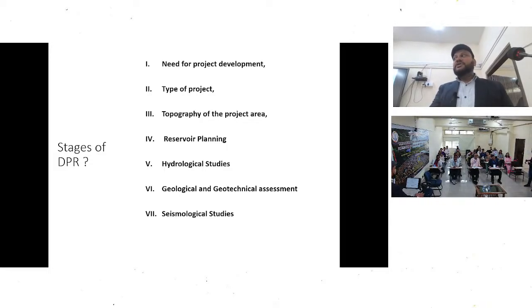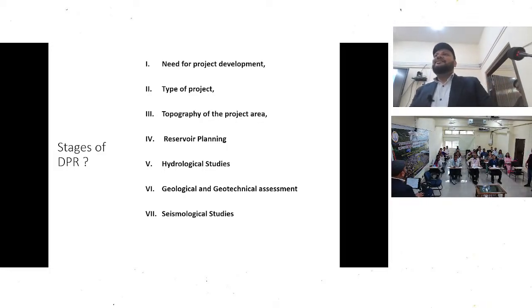The topography of the project area: if we want to construct a dam in, suppose, a plain area, Majuli or some Guwahati, then what will happen? The reservoir will inundate whole Guwahati, the whole area. So it is not feasible. And we have to plan reservoir planning, hydrological studies are also required, geological and geotechnical assessment is required, seismological studies are required, whether that area is